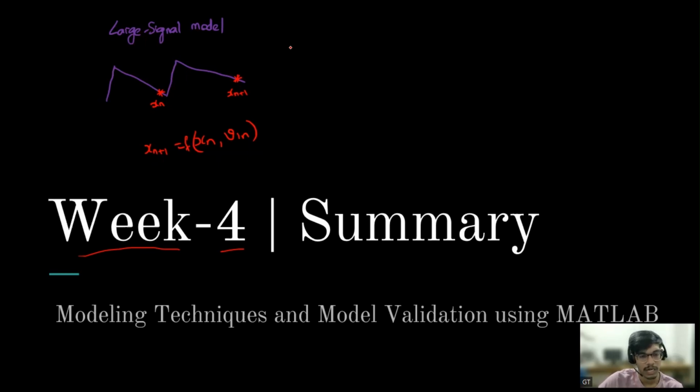So using the equation x dot equals ax plus bu, and y equals cx plus du, where d is 0, so y equals c into x, we have got this expression because we have considered different modes. This delay is one mode, and until this point is one mode. So this is mode 2, this is mode 1, and this is mode 2. If you go back to that slide, here the matrices are A, 0, here A, B, here A, 0. So using these equations with the corresponding matrices, we got xn plus 1.